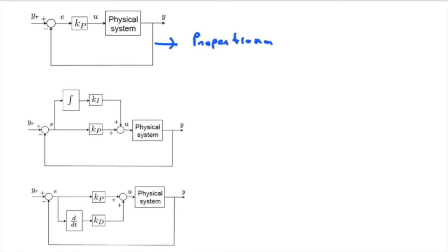So this is your open loop system here, right? This is the system given to you. And so the transfer function is what? A ratio of y over u, right? That's the transfer function we have, or your plant. It does not have to be a transfer function. It can be a state space, whatever system is given to you. And the idea is, I give a u, you get a y. But we want to move forward, right? We want to say, no, I want my y to track a reference input. So I want it to be a desired output rather than just any output. Okay, so this y can be your phi, which is the roll angle in the aircraft.